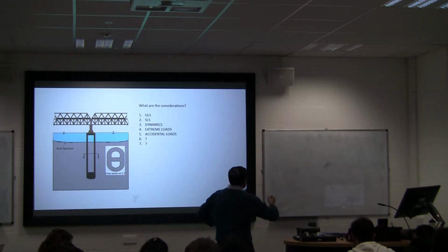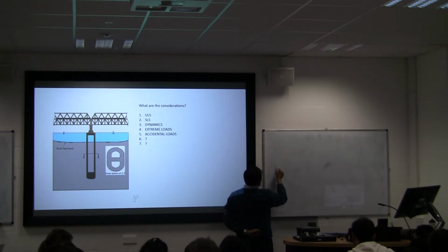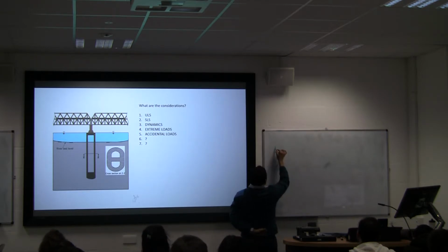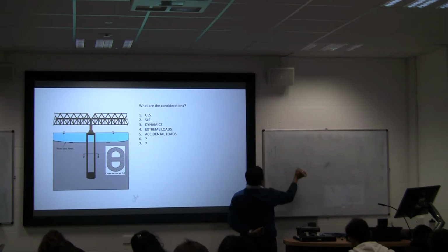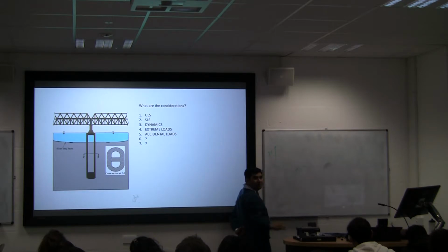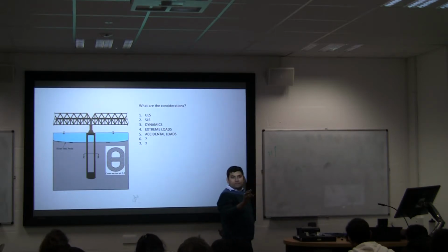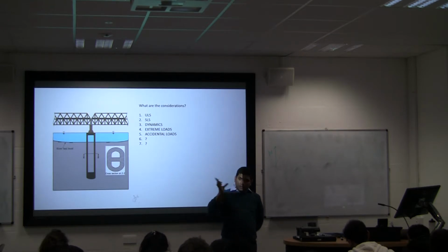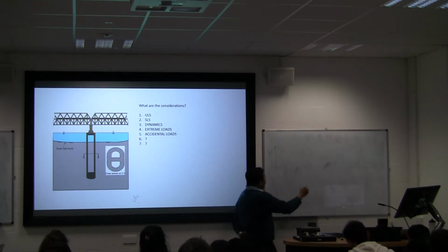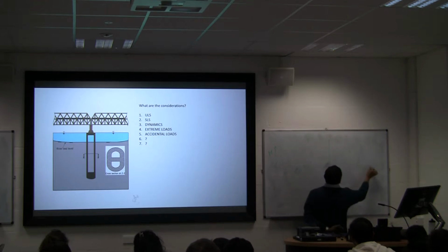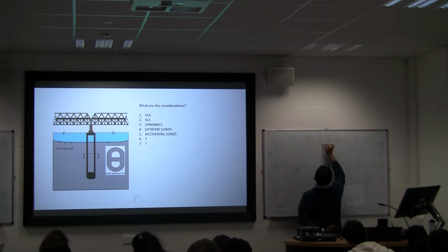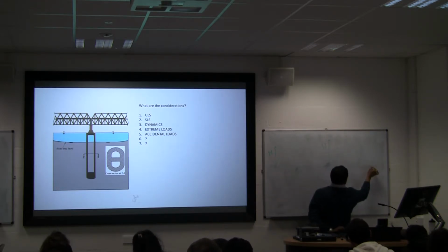Stiffness means you want to know moment versus theta, of the foundation: what moment will give you how much rotation? Or you might want to know lateral load versus displacement.